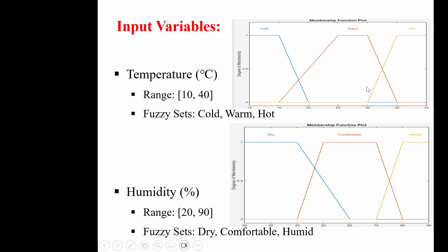So the same thing here, there is need for the overlapping at a certain point. And one thing we can do is that when you draw your membership function, you capture the information from the environment where the fuzzy logic controller is going to work, so as to be able to get the correct scenario here.